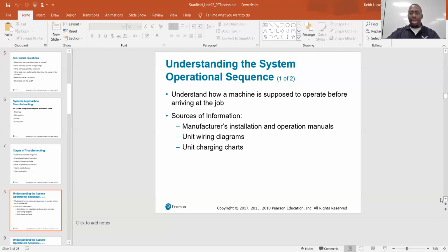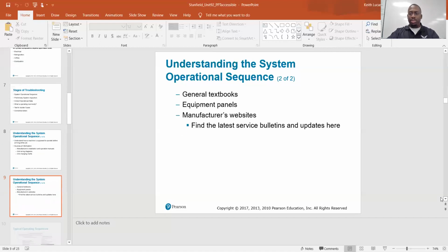The most common way I use the wiring diagrams is to trace out what's in front of me and compare it to the diagram and make sure that things were done right. If not, I'll go ahead and make the correction. Sometimes things will be altered, but not necessarily in a bad way. Some accessories may have been added after the initial install. So when you do see something that's different, just trace it out and see what it's there for.